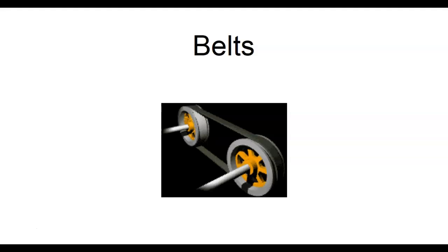It's got a little slack in it, so it's more forgiving, like with motor stalls or something like that. It's not considered positive drive because there's always a little bit of slip in a belt drive. So we wouldn't use this on something where we had to maintain a perfect speed or a good speed. We use either gear or chain.